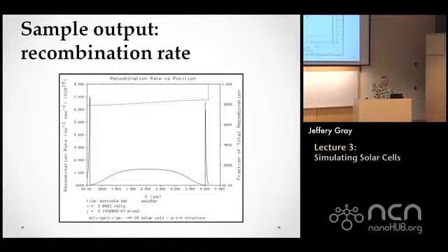And actually what this says is that because this dashed line starts out almost at the surface, something very close to the front surface of this device is creating a lot of recombination. And at the back, it looks like 15% of recombination is just occurring right at the back contact. And these spikes in recombination really aren't important at all, because they're not adding anything to the recombination current.